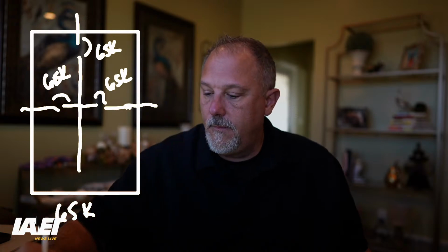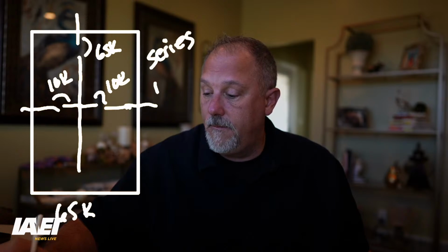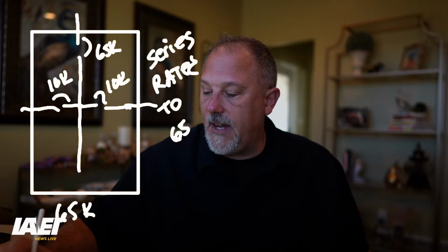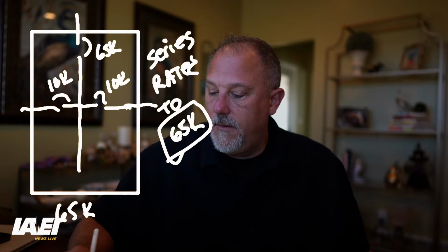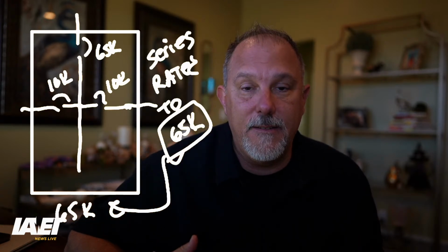Or if these are 10K and these are series rated to 65K, then the rating of that equipment is 65K. Make sense?